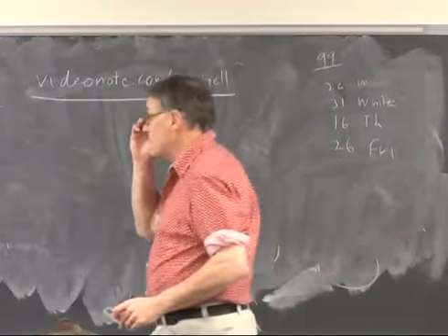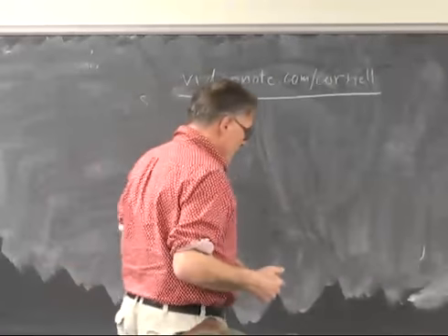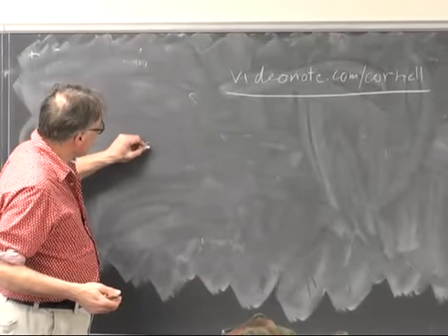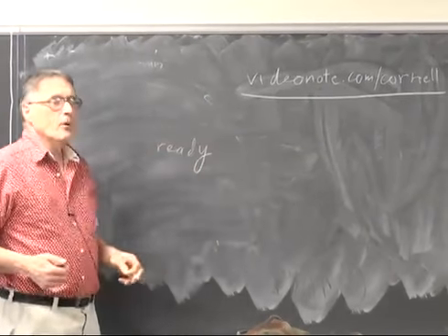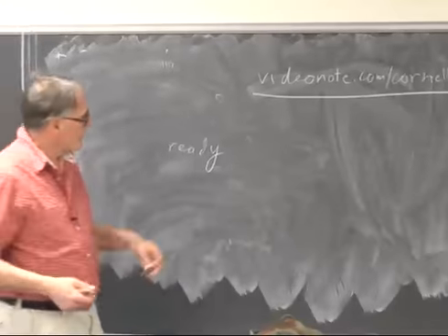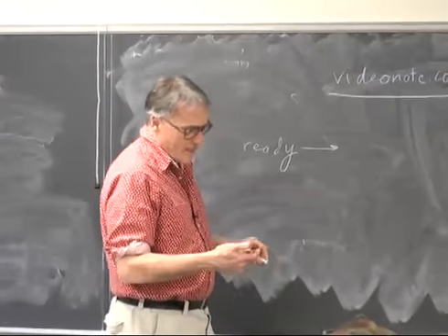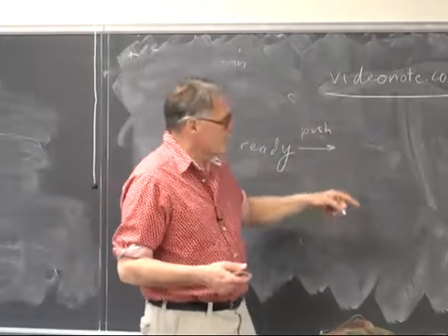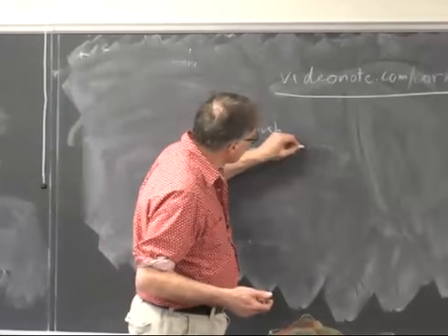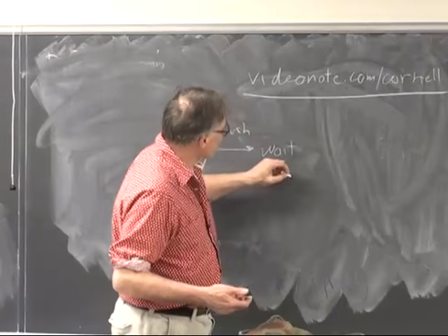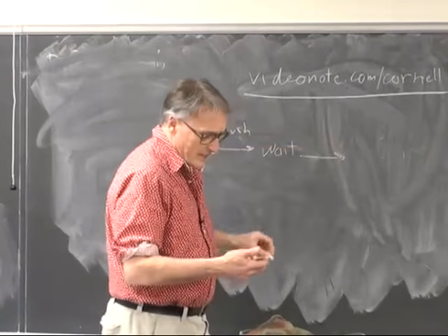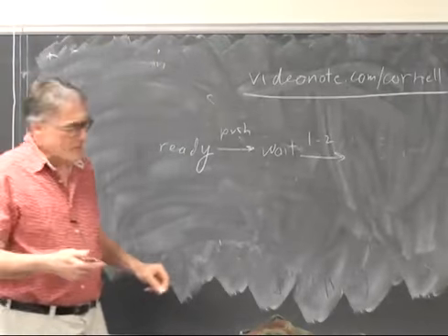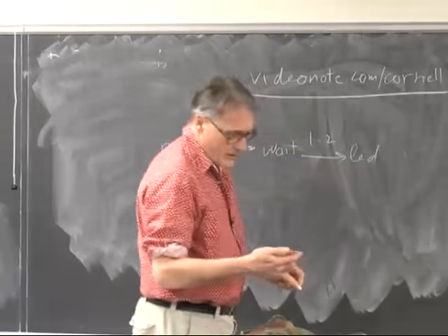Lab 1 has one small trick that probably some of you have detected. There's a state which I'll call ready, where the LCD is saying ready, and a push button takes it to the next state, which is a wait state. The transition to the next state is 1 to 2 seconds randomly, at which time an LED and a buzzer come on and the lights flash.